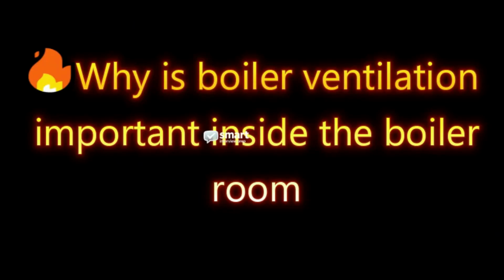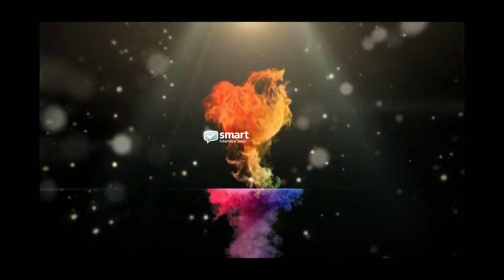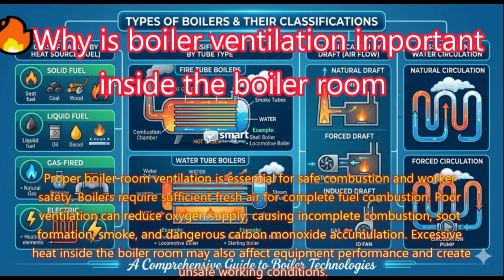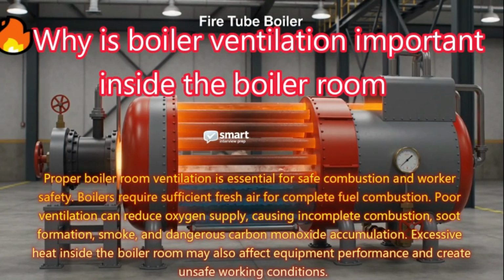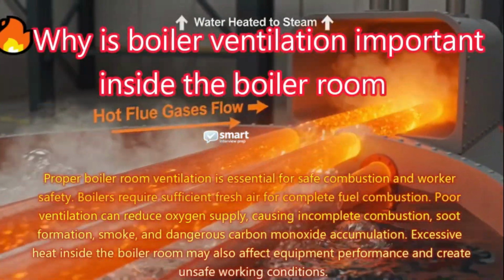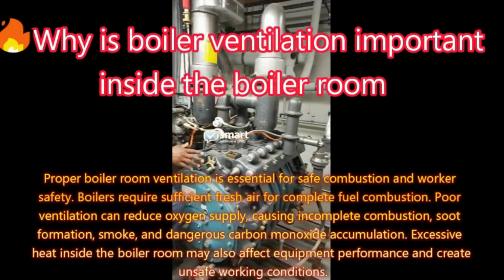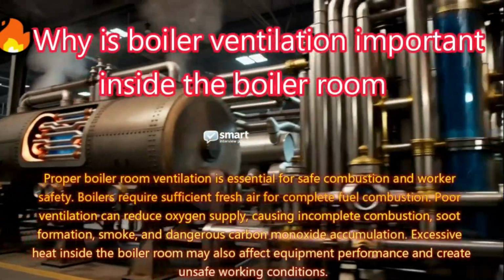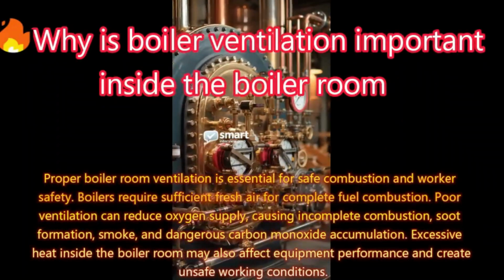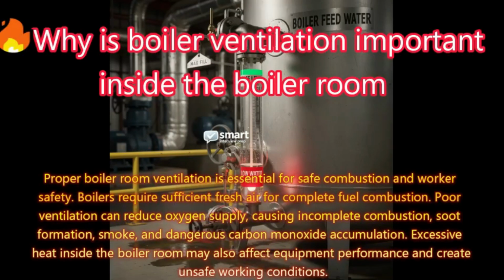Why is boiler ventilation important inside the boiler room? Answer: Proper boiler room ventilation is essential for safe combustion and worker safety. Boilers require sufficient fresh air for complete fuel combustion. Poor ventilation can reduce oxygen supply, causing incomplete combustion, soot formation, smoke, and dangerous carbon monoxide accumulation. Excessive heat inside the boiler room may also affect equipment performance and create unsafe working conditions.